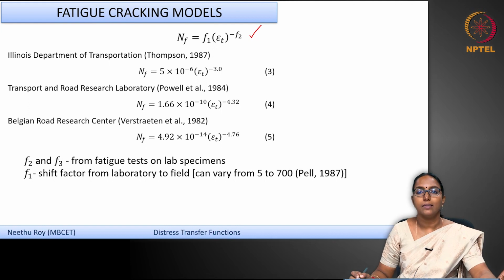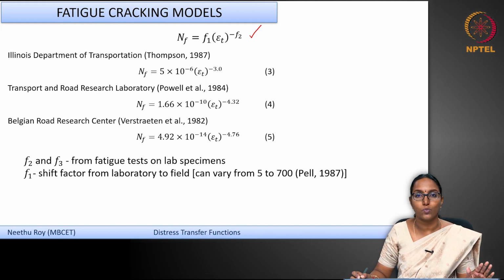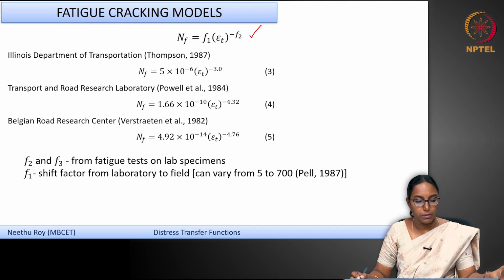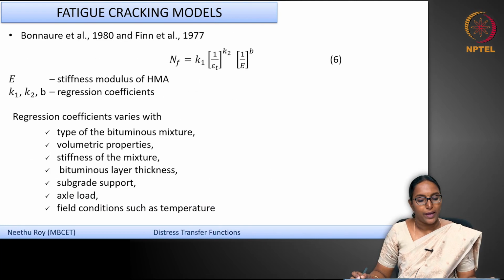So, this highlights the importance that whenever you want to use these fatigue cracking models, it is necessary that they are well calibrated and that the field performance is properly captured through this F1 parameter. Okay. So, again, as I said, certain models have neglected the influence of E, the material modulus, but certain have considered that as well.